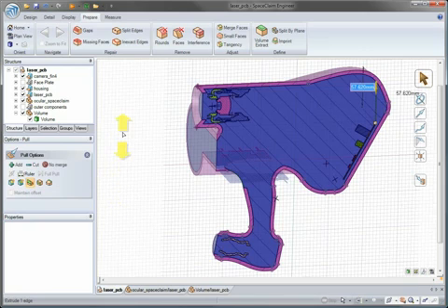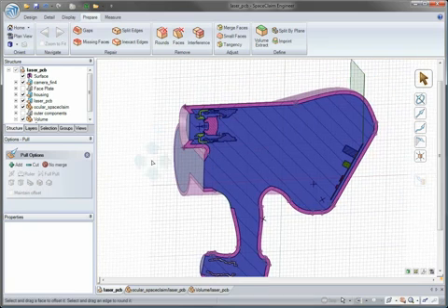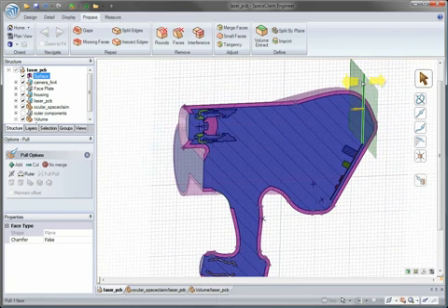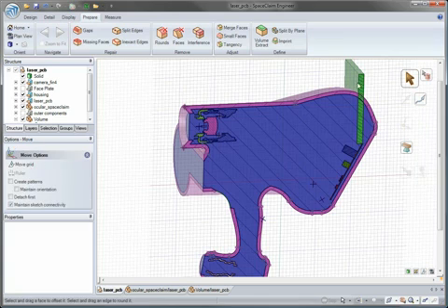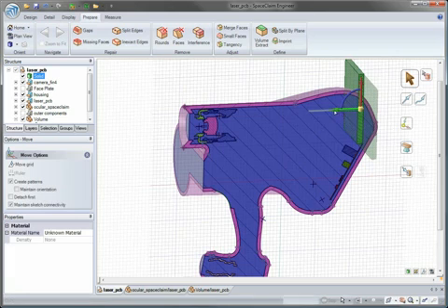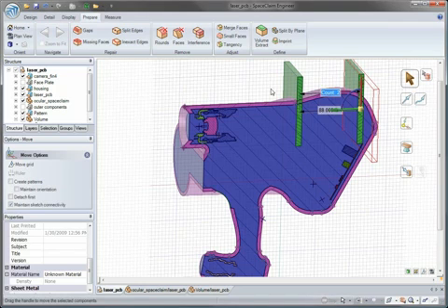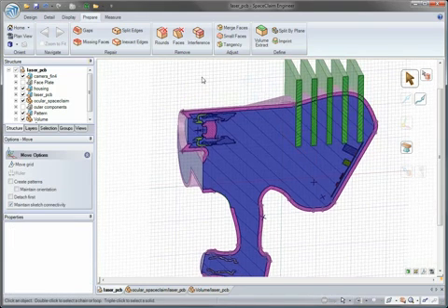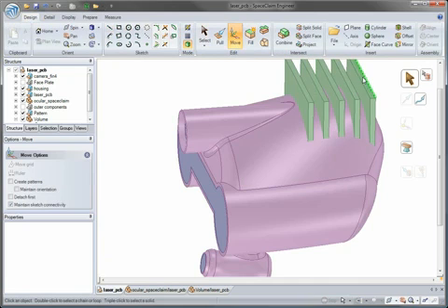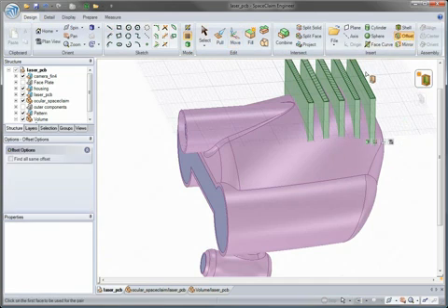If it's still too hot inside the housing, another solution we might recommend is that slots be added to the top of the housing. In SpaceClaim, we can create geometry both in 3D and in a 2D environment. We can quickly create a solid and pattern it over to create as many slots as we need.